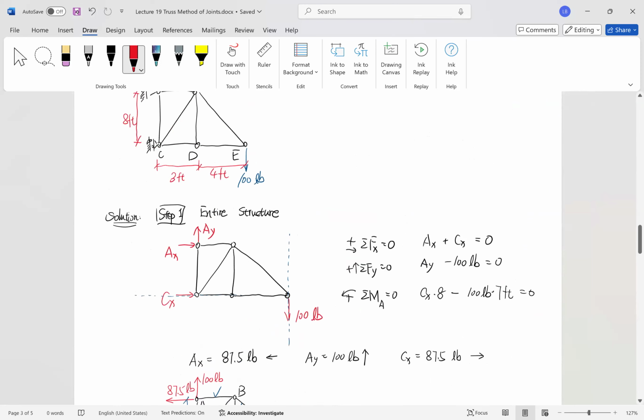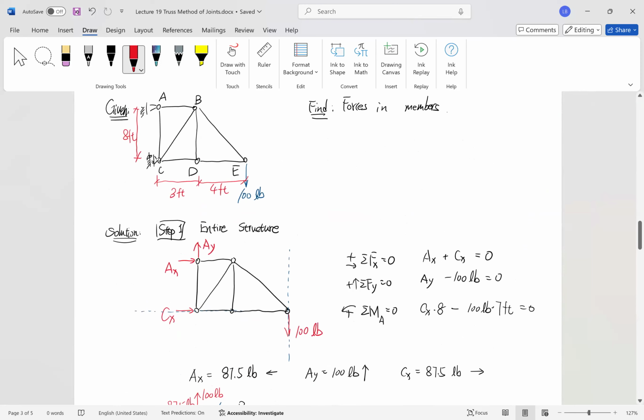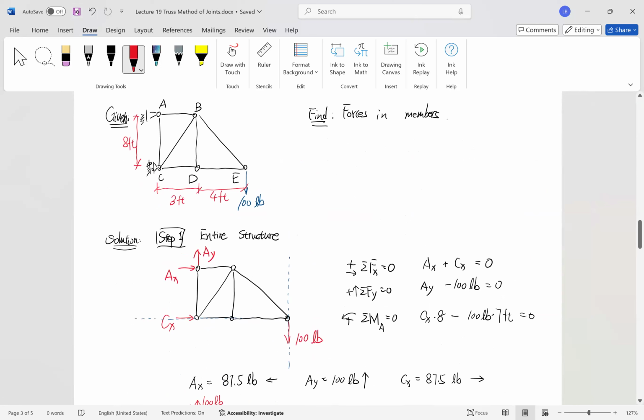And we see that the main takeaway is that when you have a truss structure and you are required to solve the member forces, in all of its members, and please note it is all, or the forces in most of its members, we can first draw the free body diagram of the structure and find the support reaction forces here.